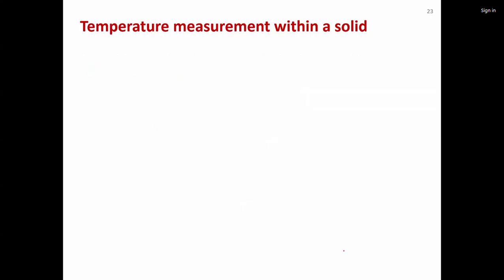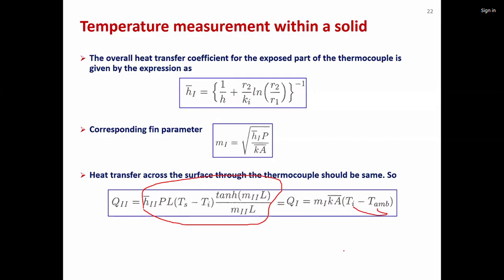So it has a meaning in the physical world also. Yes, it has meaning that as compared to the cross section, if the length of the fin is large, typically much greater than the diameter, could be 10 or 20, then you call this a long fin.